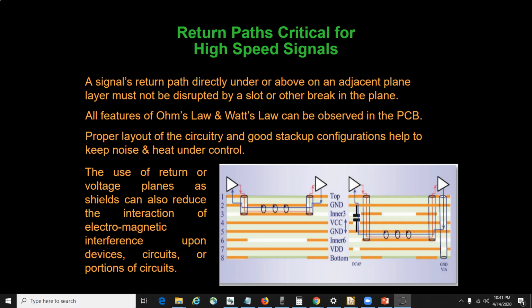So here we need to make sure that we have a short return path in the PCB when designing the circuit. The other thing we can do is use ground shielding. As you might know, a ground metal plate greatly attenuates electric fields. Stray electric fields, including radio frequency fields, can be effectively shielded using a metal enclosure that surrounds sensitive components.